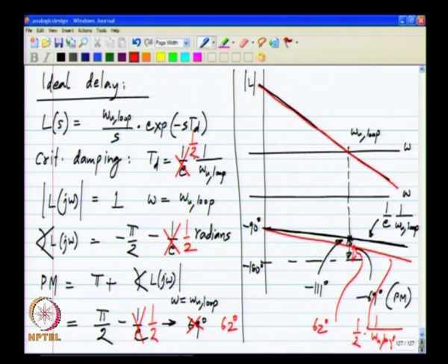So, let us say you are trying to make a negative feedback system whose integrator has a unity gain frequency of omega u loop, that is the loop gain is supposed to be an integration and it has a unity gain frequency of omega u loop or a time constant of 1 by omega u loop, then the excess delay can at most be half of the time constant, okay, and that is a reasonable thing to remember as well.